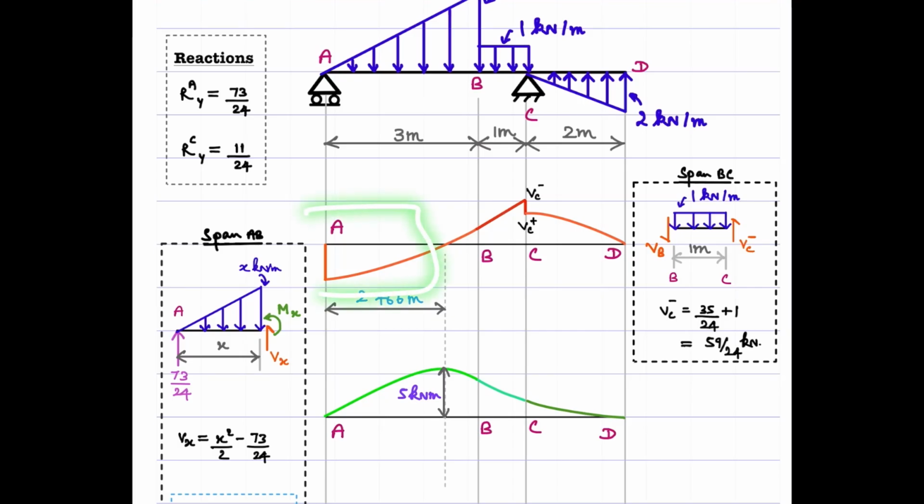So here we need to consider this portion separately, this separately, this separately, and this separately, because each of them shows a particular pattern, right? So for this portion, this is the way the bending moment diagram should vary, right? So the slope here should be positive and it has to gradually decrease until it reaches a zero value here. Okay. So only then it can be related to the negative ordinates of the shear force diagram.